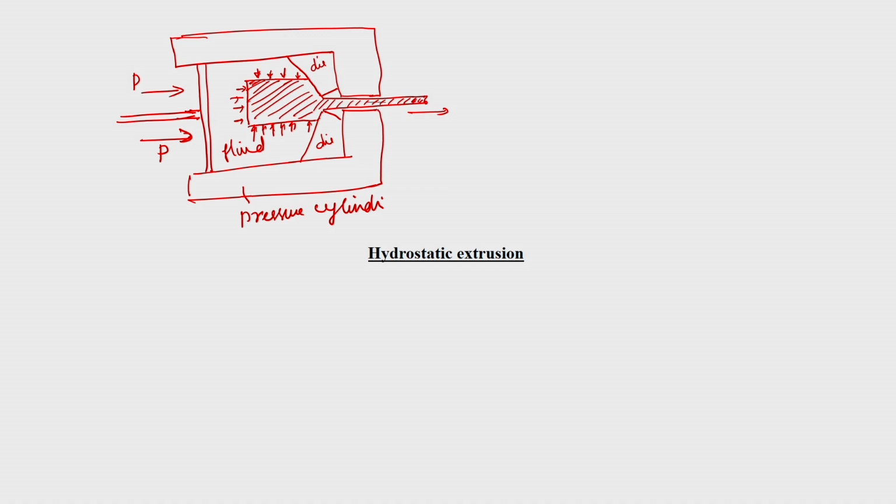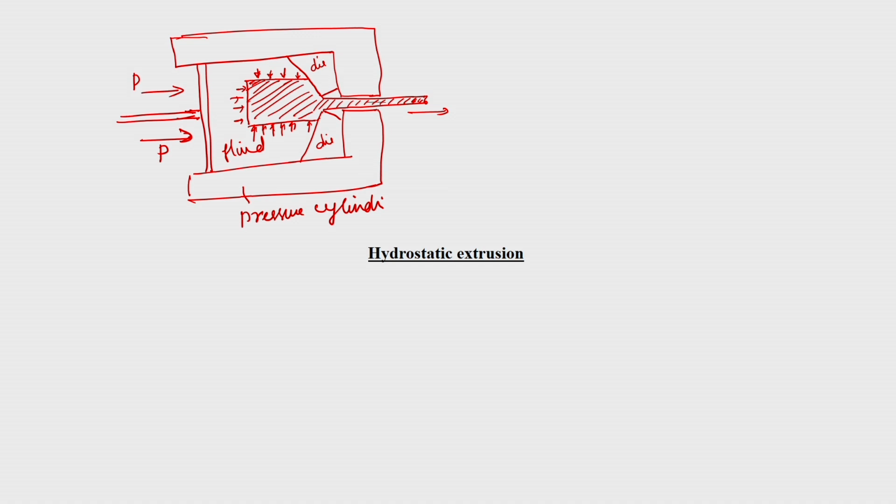But in this hydrostatic extrusion, that also is not there, because there is no relative motion between the die and the workpiece. It is compressed in all directions and then it just ejects it out. That is the biggest thing under the hydrostatic pressure, where at the interface there is no restraint or constraint. So, the metal moves through that region only. So, that is one advantage.